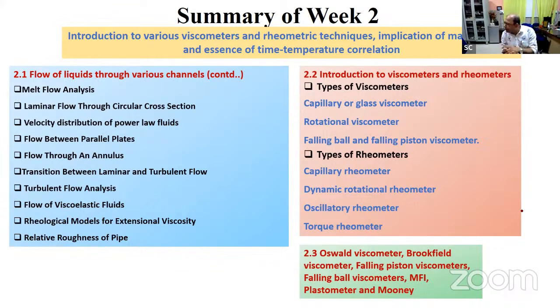Okay, so for plastics, say for example, MFI is good enough. MFI is where you have a specified load given at a certain temperature. With that given load, how much is flowing at a given time across a particular length of capillary. Nowadays, MFI machines are becoming more like a capillary rheometer rather than isolated, single, discrete loadings and flow patterns. You can do it at variegated loading conditions, variegated temperature conditions, and whatnot.